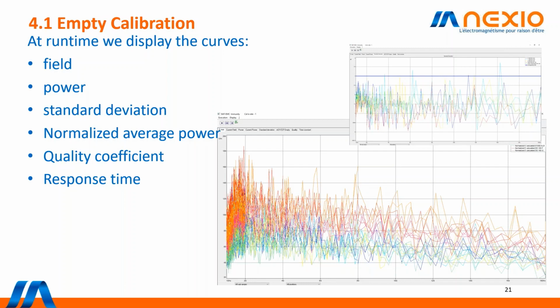All the monitoring we have in traditional conducted and radiated immunity tests with EUT control: multimeter, oscilloscope, data logger, camera, CAN bus. All of these options we have for monitoring are obviously available also for reverb testing.